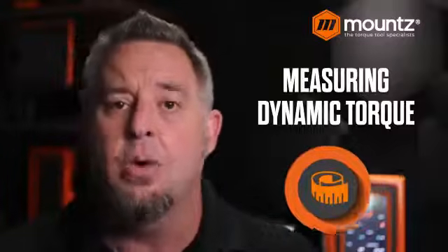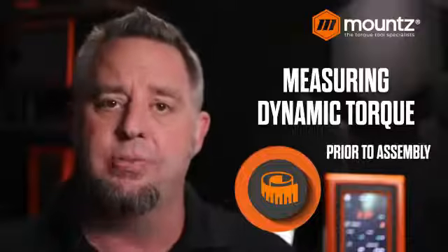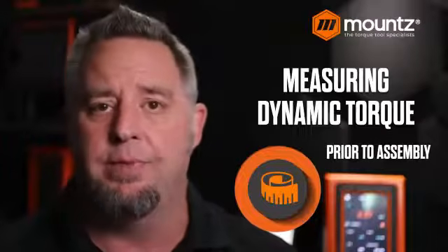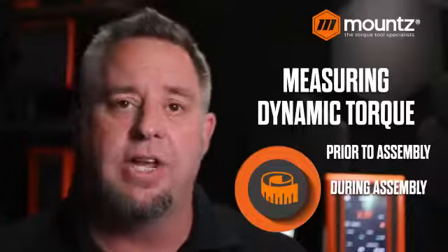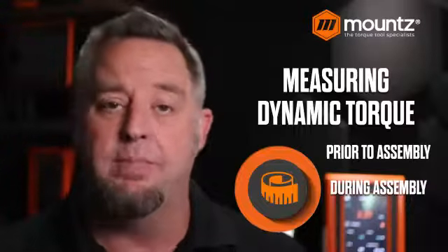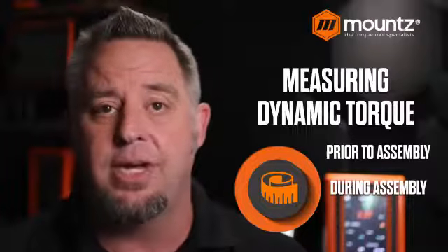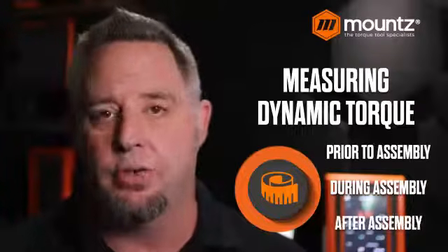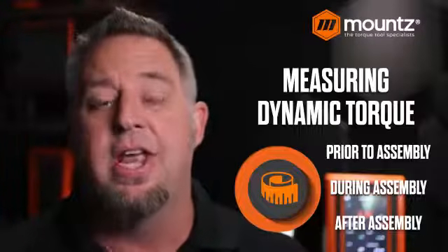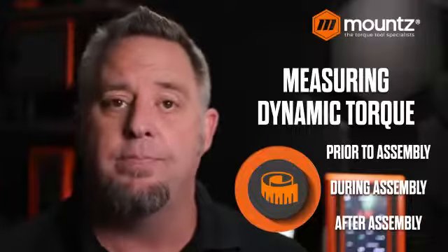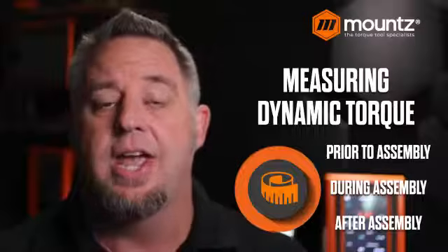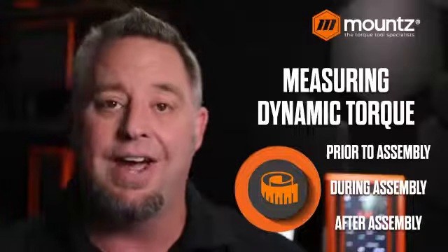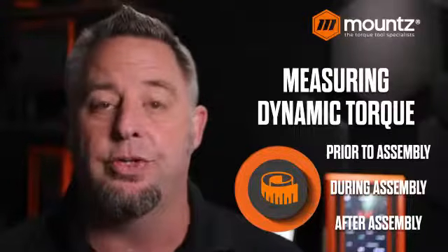So when we look at when we can do the measurement of the dynamic torque, there are basically 3 different areas that we can look at. We can obviously measure before the assembly process. So we could set the tool up on a joint simulator and run that tool down. We can do it during the assembly process. And then we can also do it after the assembly process through some auditing.